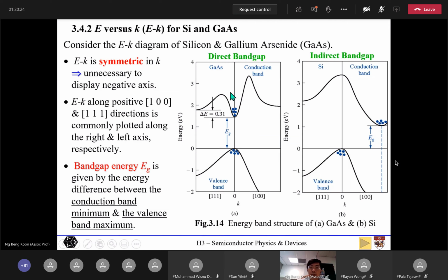All right. So what's the difference between these two types of semiconductor material? If we look at the direct band gap semiconductor material, if you have some electrons in the conduction band and some holes in the valence band, then for an electron in the conduction band to get down to the valence band, this can occur quite readily.